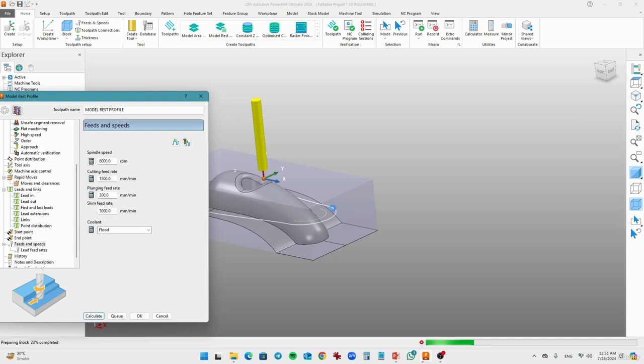One thing you have to notice is that we have applied limits here. The boundary in white color represents the boundary, and in the limit boundary we select the trimming option, trim inside. So the cutting tool will perform its operation inside of that boundary. It will not work outside.